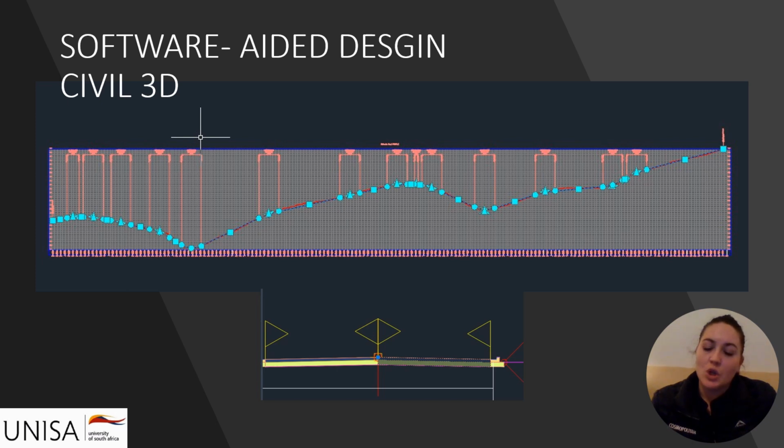If the contours are closely packed together, the road is quite steep at that particular point. If they are far apart, it can be quite flat, which can cause drainage problems. These can then be changed on the vertical curve. Where necessary, the heights of the curve can be changed. Then you just rebuild the corridor to give a better visual representation of the road.